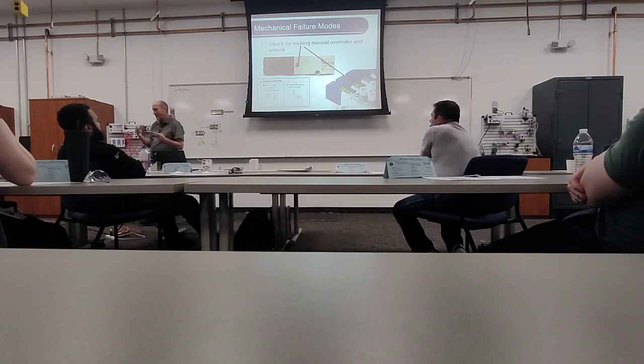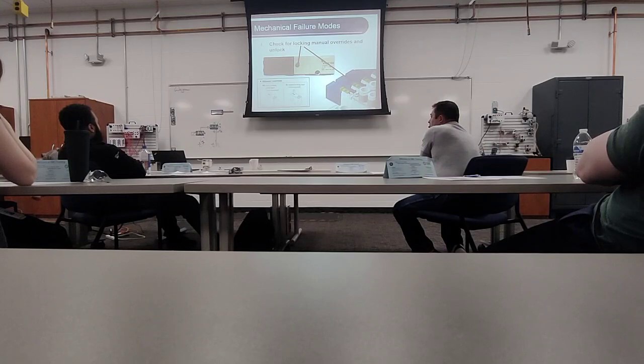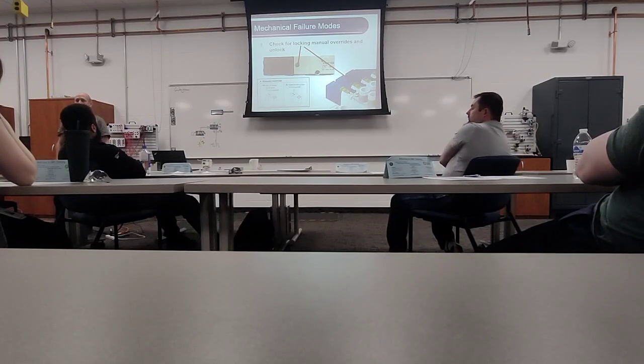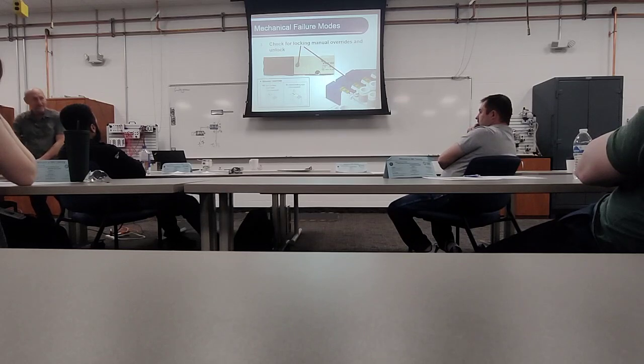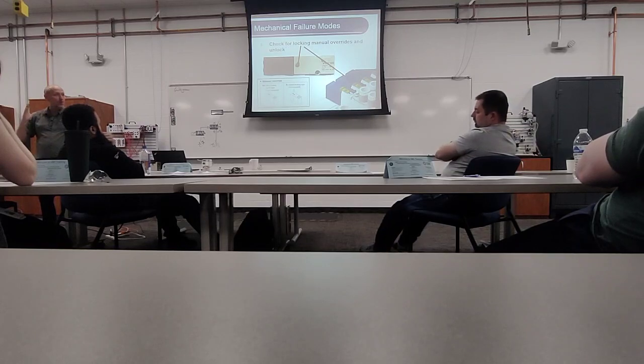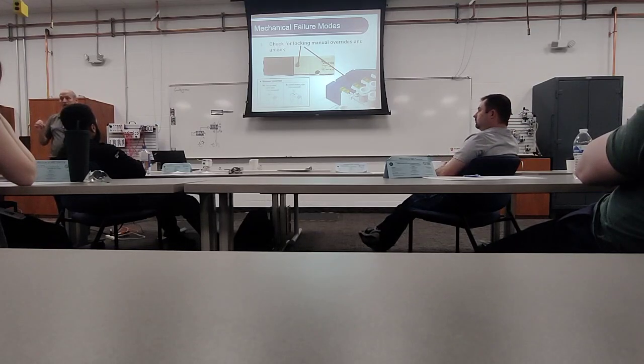Or it could be something like this. You're gonna hit an override on this one and you think you're moving this actuator. I'm sitting down there underneath here, it's dark on this manifold. What's it gonna take for me to press the wrong valve, the one next to it? Now I move the whole wrong actuator. Or I move an actuator and when it goes, it hits a switch, and then when it hits that switch, it starts the other part of the machine up, and I didn't intend to have that happen. If you don't understand what's gonna happen when you hit an override, don't hit the override.